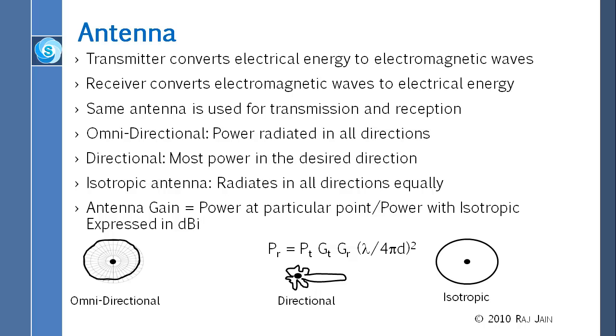All right, and now we are not going to go into this whole formula derivation, but the idea is that if you had a dumb antenna, then they will not provide you any gain. So both of these numbers will be 1, and your received power will be strictly proportional to the transmitted power times (lambda upon 4 pi d) whole square. So as you go more and more, the d square is with that r square we were talking about. The area keeps going up and going up, and so your power keeps going down and down.